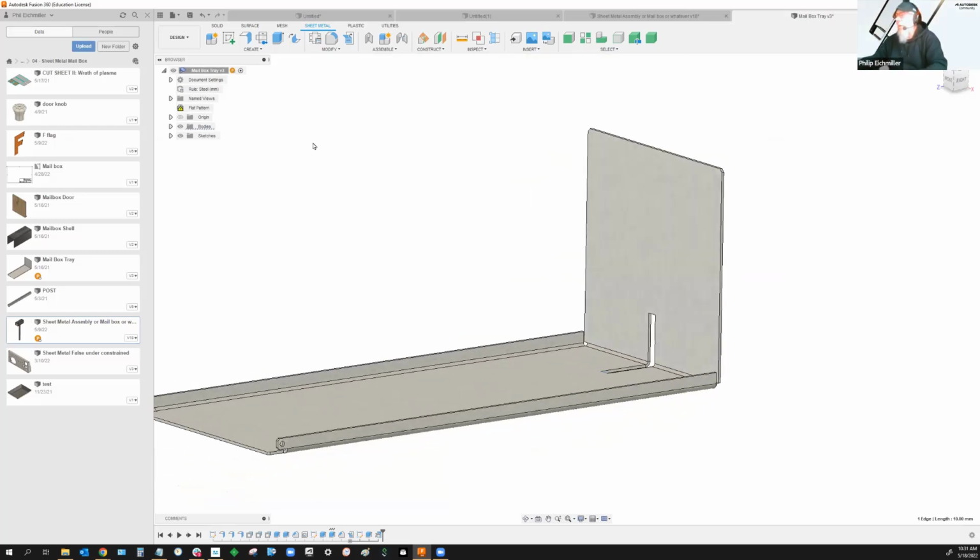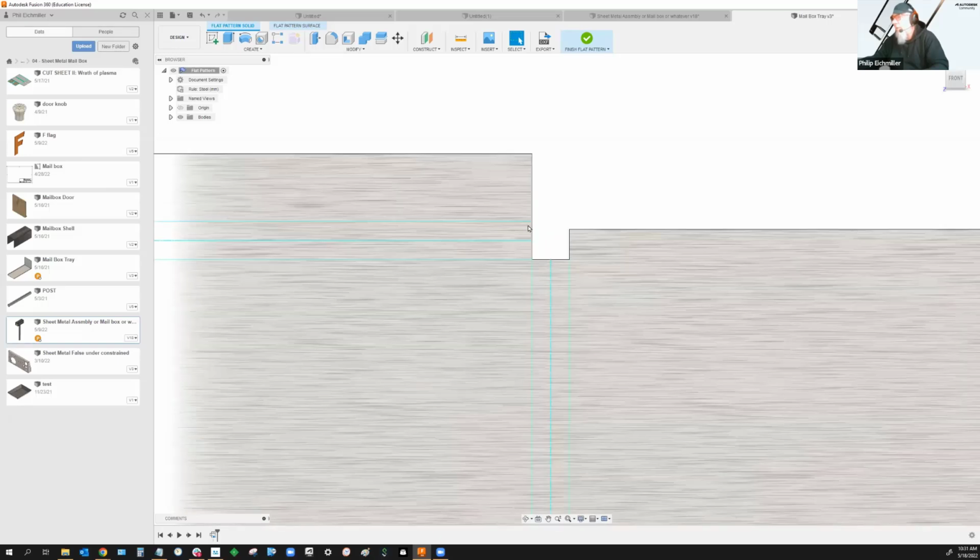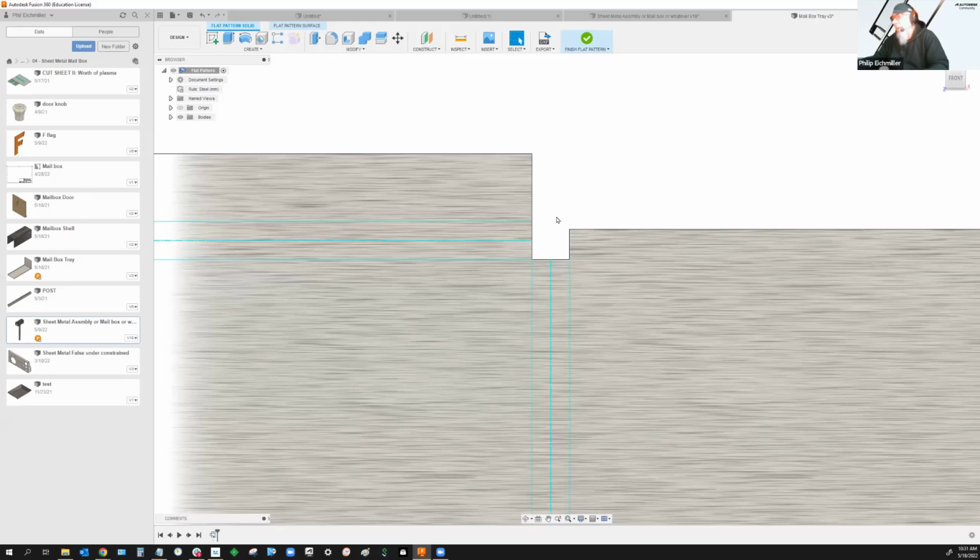Well, so the reason you can edit a flat pattern, right? Does this have a flat pattern? Let's edit this. The reason you can edit a flat pattern is because there needs to be that flexibility there, right? So all of the sheet metal parts I used to make would either be cut on a laser or made on a turret punch, and those machines sat side by side. And so the turret punch is going to get real picky about how you make these bend reliefs, right? The laser didn't really like square corners.